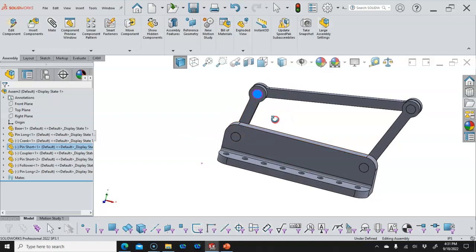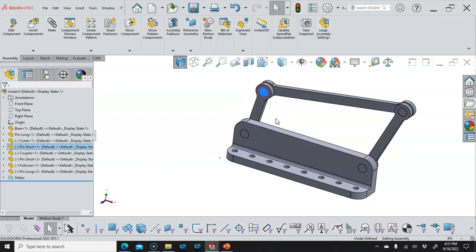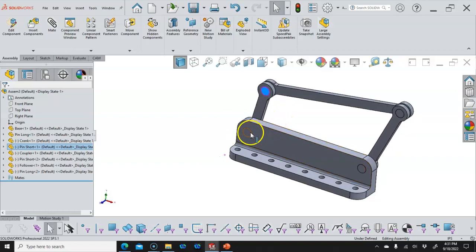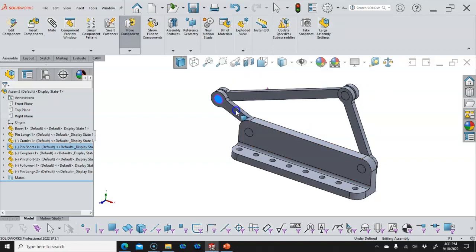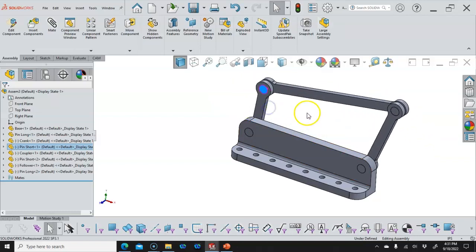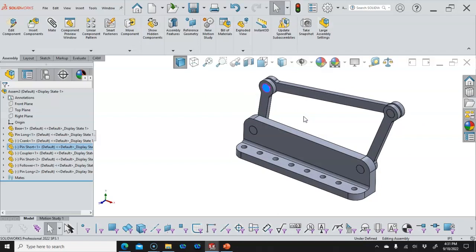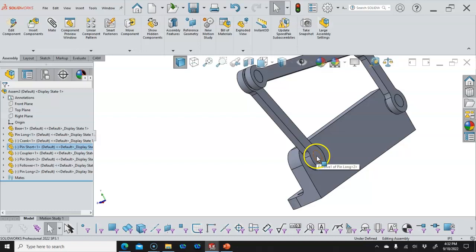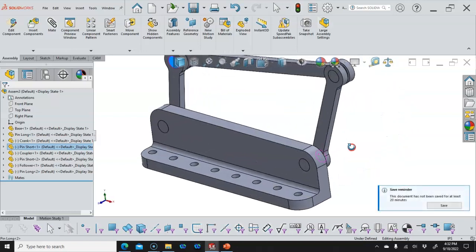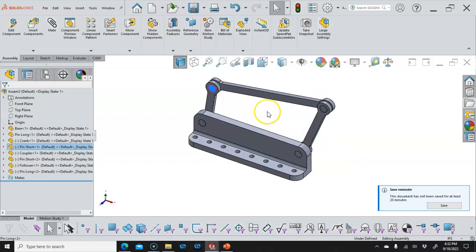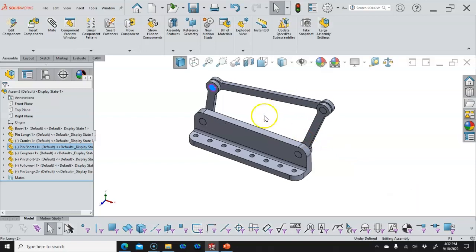Going into the manufacturing side, whatever this is doing, if we're driving this with a motor, if it's pulleys and belts or some other way of creating some kind of intermittent motion, it can go through its movement, that whatever we're producing here, we'll want to look at that and do the constraints, because just a press fit and an unconstrained slip fit between those couplers, the pins, and the arms is not going to do us that much good.